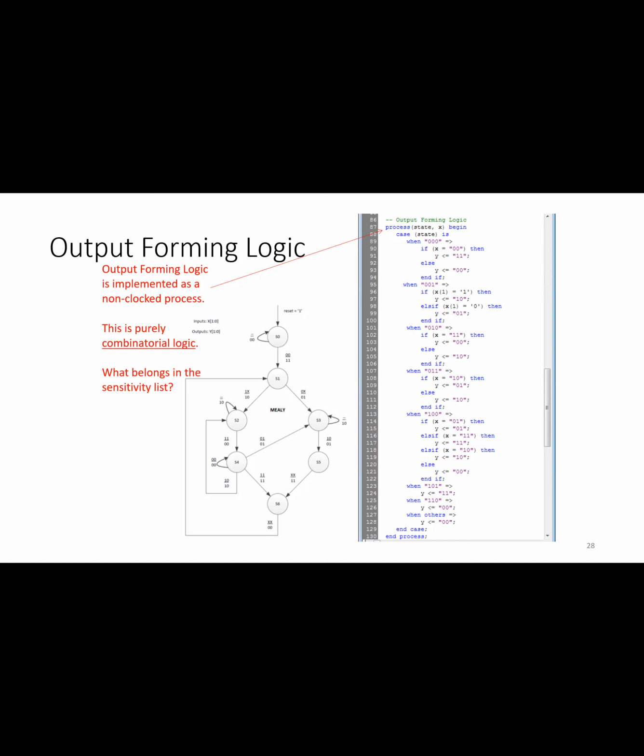Do you know what a case statement is? No, I'll be honest, I don't. We are moving from one choice to the other, like if statement, according to the value of state. When I say when 0, 0, 0, that means state should be 0, 0, 0. When I say when 0, 0, 1, state should be 0, 0, 1. Got it. Moving from one case to another.